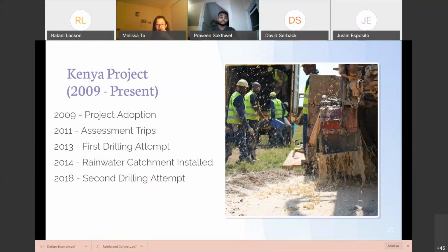So at that point, you have to really consider a lot of things at that moment in the project process. For one, you have to understand that drilling a borehole well is not necessarily a very quick process. So you have to take a lot of time to really determine where you want to drill. Just like you don't want to end up in a situation like we did in 2013 where we drilled dry. You want to make sure that where we're drilling actually has water. You want to be very consistent and precise with your surveys and make sure you're picking a really good spot. And you also want to make sure that you're hiring the right people to do it. And also financially, it's just a very expensive operation. So it was looking like a 4 to 5 year setback.